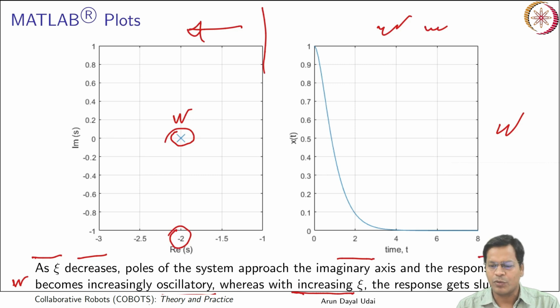I have given some examples to make you understand. You just have to remember where, in a second order system, those roots should lie. They should lie in the left half side, and preferably we would prefer to get this, but if not this, you should be happy with the critically damped case, or better an overdamped case, but definitely not an oscillatory nature, and pure oscillation is definitely very bad. It will infinitely keep on oscillating. So those are the undesirable cases.